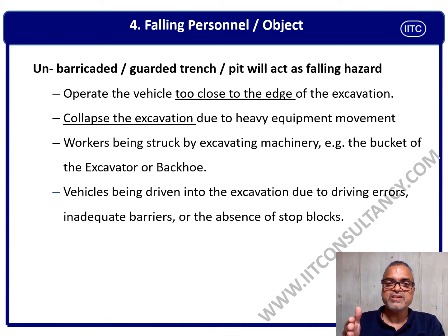A worker being struck by an excavating machine, for example, the bucket of the excavator or backhoe. This also has to be considered during the excavation activity. Vehicles being driven into the excavation due to the driver's error, inadequate barriers, or absence of a stop block. So I mean to say that being a serious and sincere employee, we have to be very clear when there is excavation. We must do hard barricading so that this can be avoided.